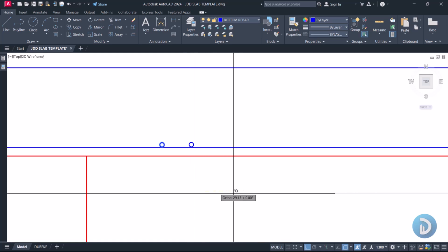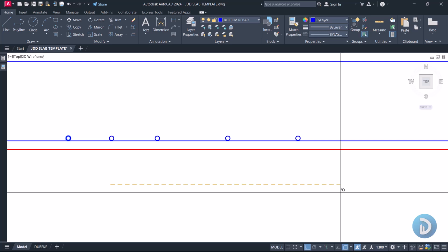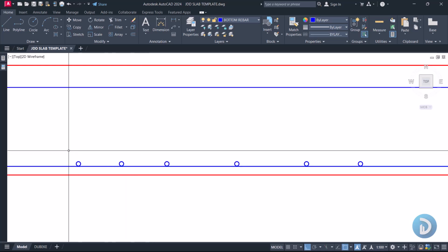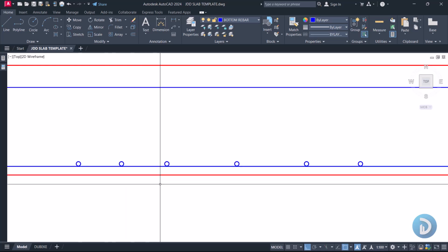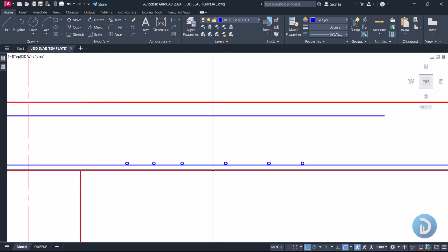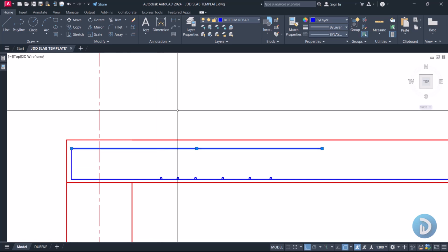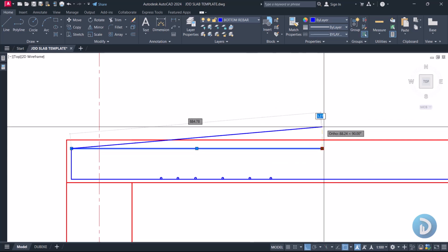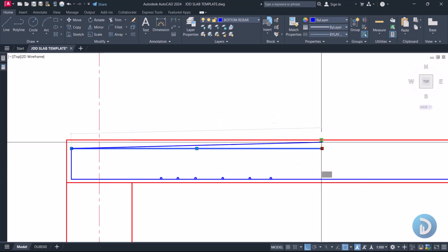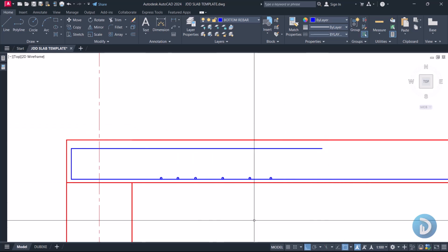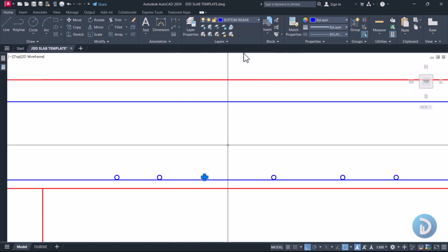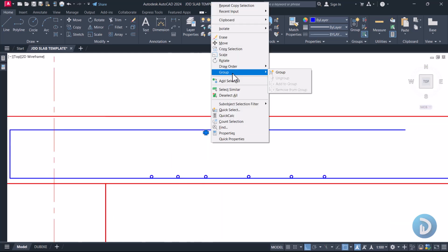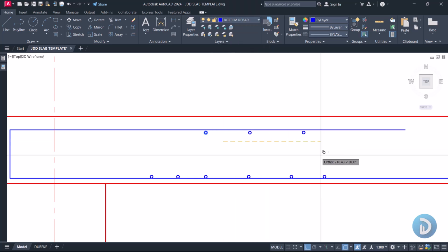So we'll be having something like this at the spacing of 200 millimeter. We have a rigid connection. We have those reinforcements at layer 1 and layer 2 connected together by our binding wire. Okay, so this will actually create a rigid base. But for our top reinforcements, if we just return this other part at the top zone, this reinforcement will be left flapping, just like this. Now we need to provide a top bar that will help to hold this reinforcement in place and also distribute the moment of this reinforcement all across the 25% of this return.